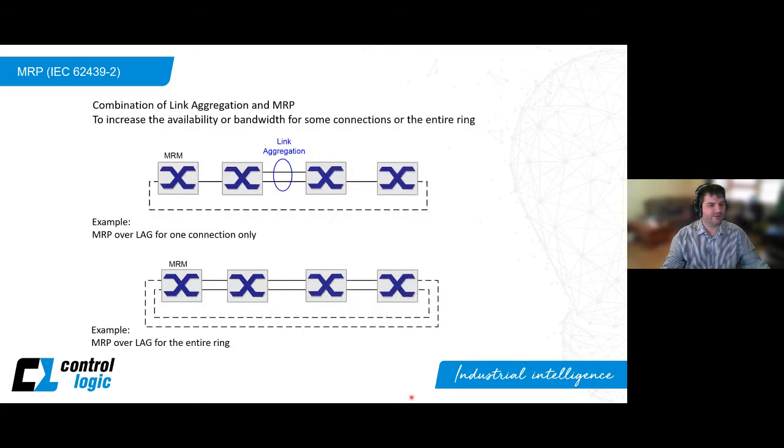MRP also has the ability to work hand in hand with link aggregation, which means that you can have more than one physical connection for each section of the ring. If you imagine something like a road tunnel, you could have a separate fiber running down both sides and a single set of hardware switches using that as one ring. In that case, in the best case, depending on the fault, you could handle 2 faults. That, of course, depends. If one of the switches was to fail, obviously, you couldn't lose another switch and still handle that fault. But if, for instance, one of the links was to go down, you could still have this other link as active, and the ring would still be in a healthy state, and you'd still have your backup links in the case of a second fault.